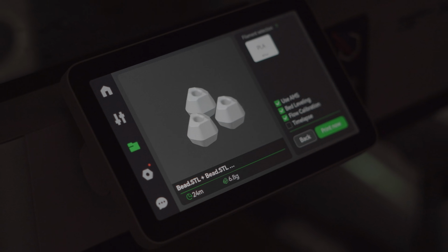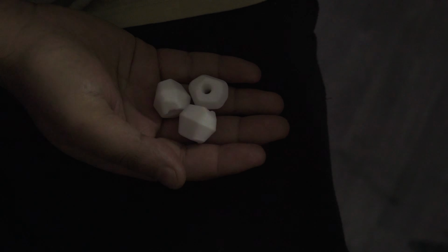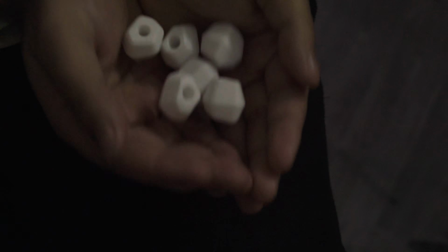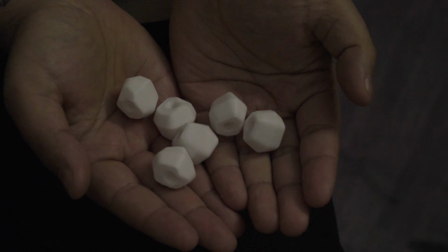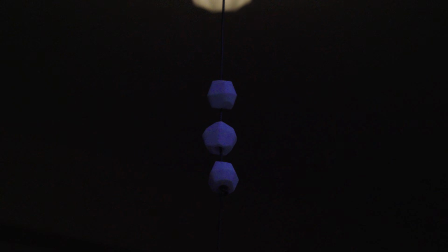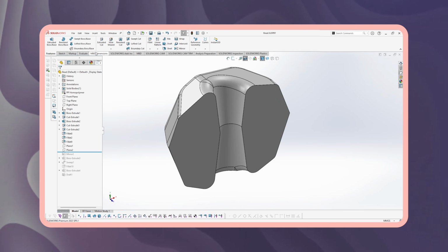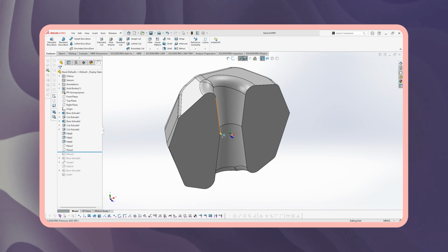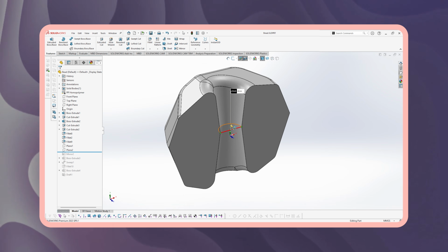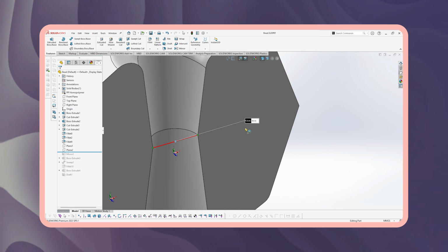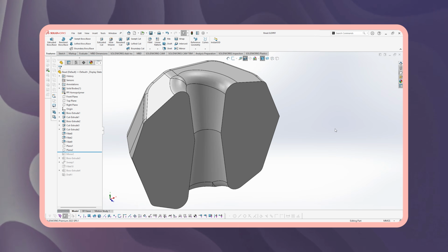After designing the bead, I 3D printed a few samples first to see how they look and feel. One thing I avoided was having a flat surface along the whole axis, because when the beads line up on a string, that wouldn't look very good visually. I also decided not to use a separate pin for the bead hole. Instead, I designed a 4mm hole with about 5 degrees of draft so the part would be strong enough and also easy to remove from the mold.